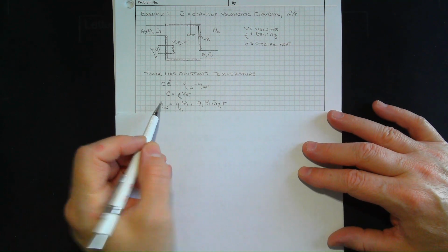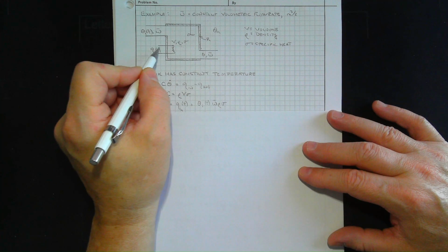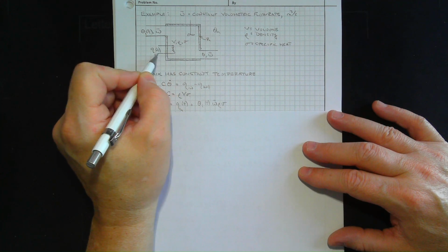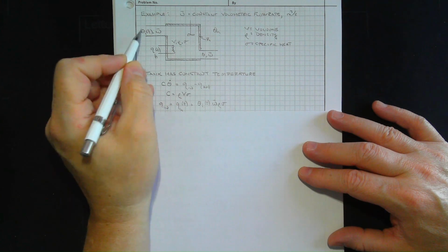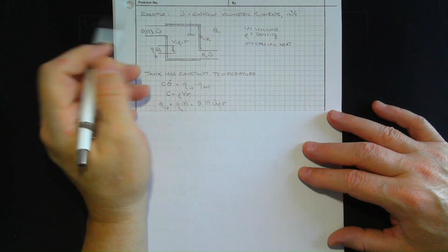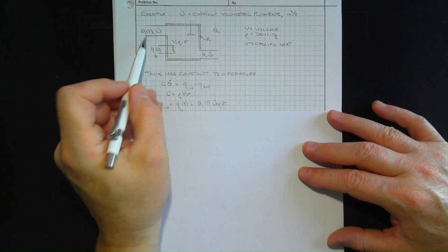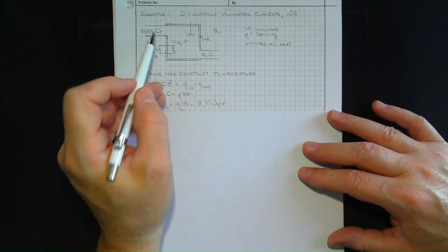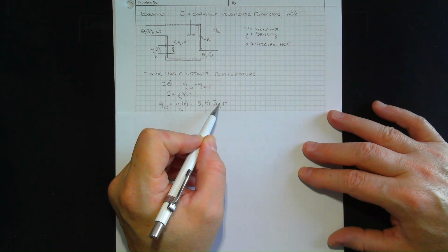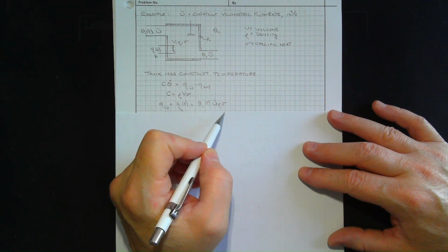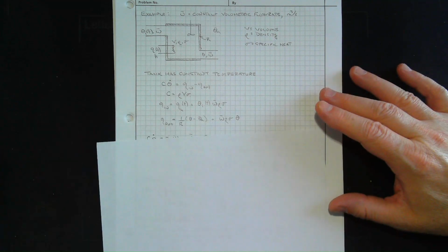So we have heat coming in from two sources. We have our heat source right here, whatever that is, QH of T. And then you have the heat value coming in from the flow. That's going to be the temperature times the mass flow rate, which is volumetric flow rate times density times specific heat. So there's heat coming in.